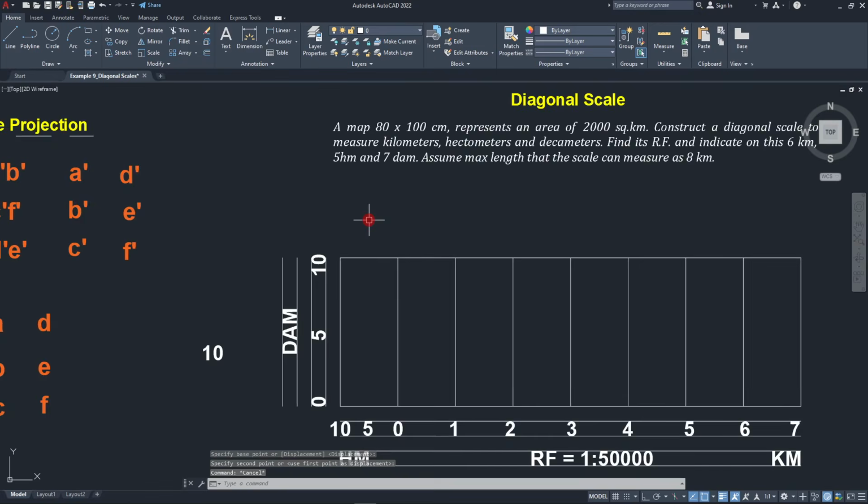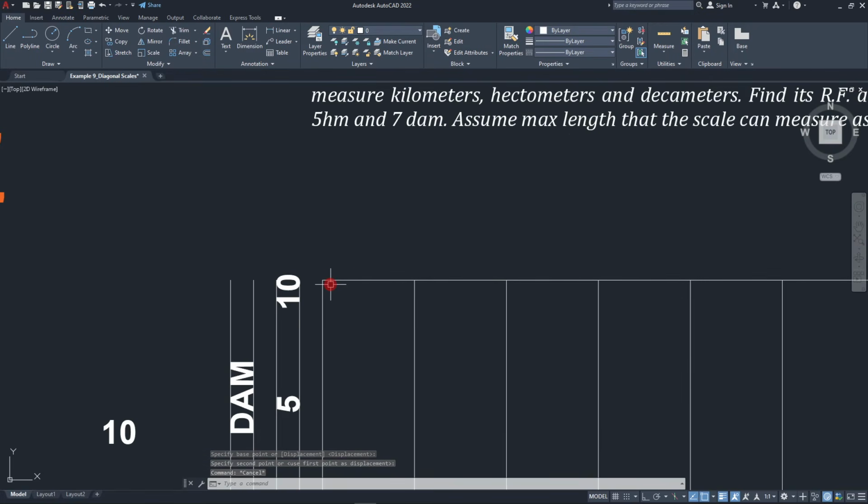As usual, this portion over here has to be divided into 10 equal parts. Click L for line and then keep the angle as small as possible. I would suggest you to go for 5 centimeters, by the way. Whatever dimension I say, it is in centimeters by default. Hit enter. Okay, and now let's begin our process. If it is 5 centimeters, at equal intervals of 0.5 centimeter, you can make these points, if you are doing it manually.